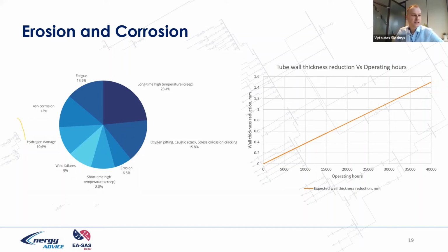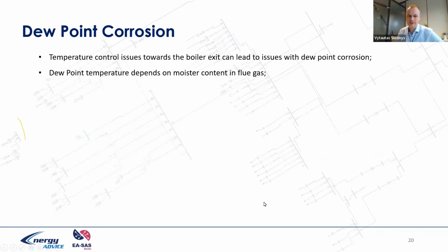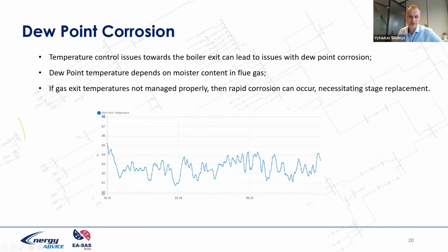The corrosion effect we can only control through flue gas dew point temperature for each component of the content which creates corrosion. For the water dew point, it's very easy to calculate because we calculate water content inside flue gas.